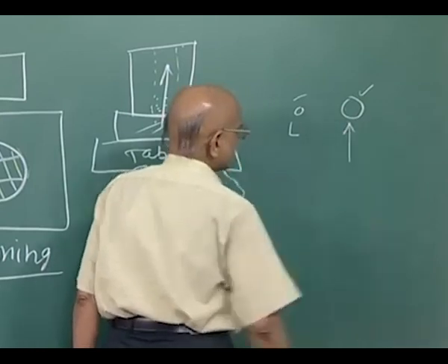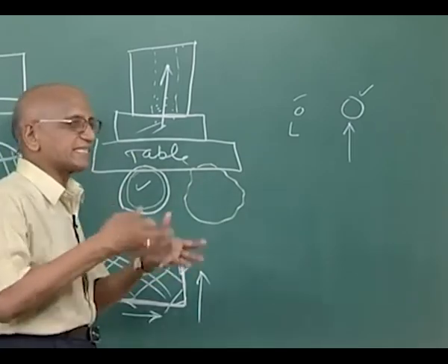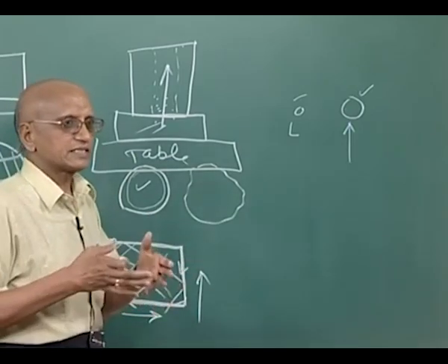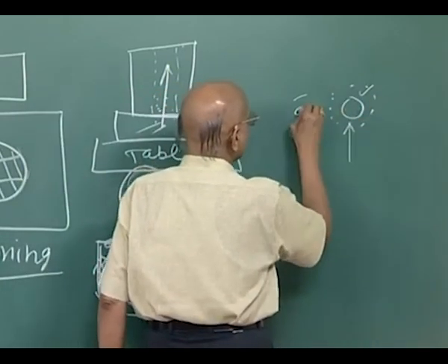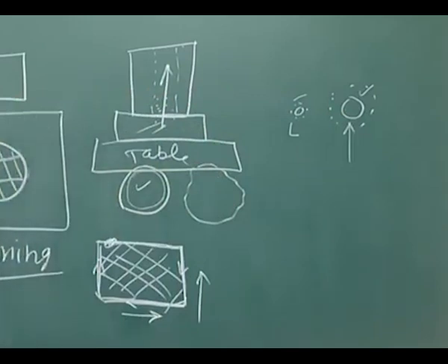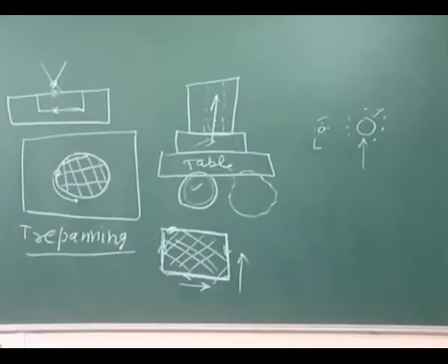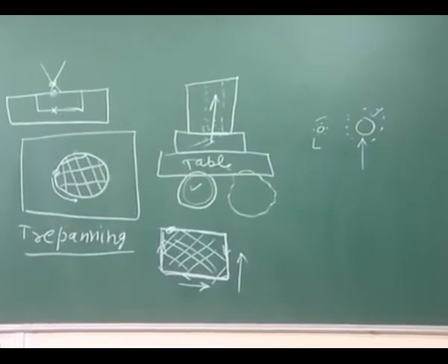However, this can also have a smaller diameter, but then because of high energy intensity, the melting of the material surrounding this will be larger compared to this, and you will have poor accuracy in case of larger diameter compared to smaller diameter, or larger pulse energy compared to smaller pulse energy. But material removal rate is going to be low, so it is going to take longer time.